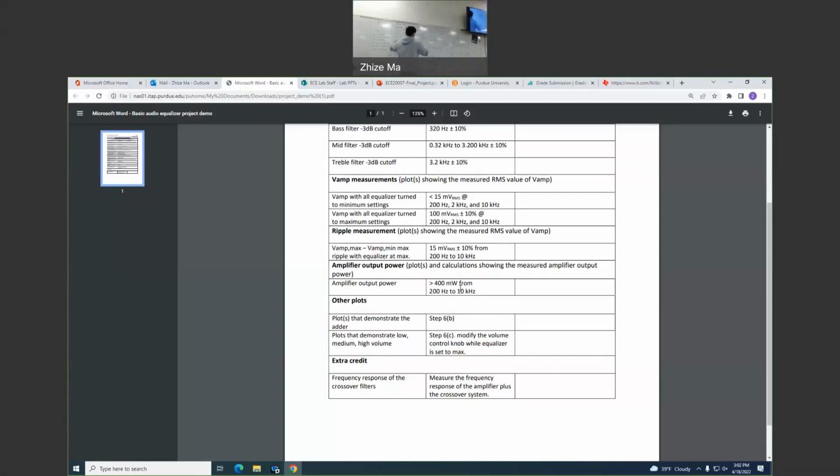So the main thing we are concerned about for the checkout part, probably after you check out the filter part, is that you're going to check out the amp power. When they use the FRA of the oscilloscope, since they can only measure when they do the plot, the unit for the y-axis is in dB. So I did the calculation. The gain they should get is negative 11 dB. Ideally, they will get a straight line when they get the maximum amp.